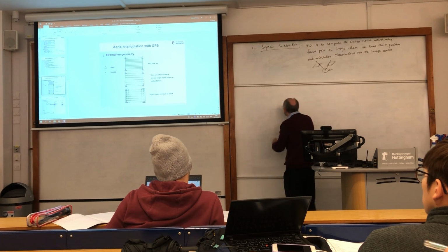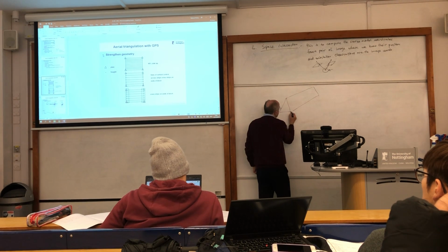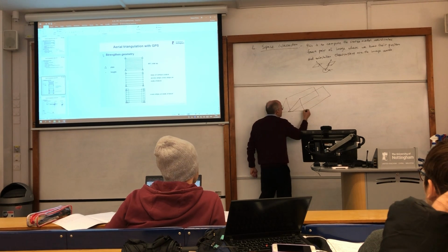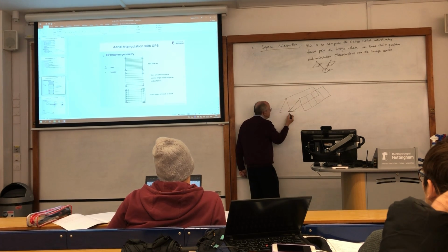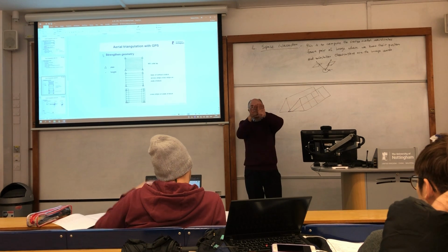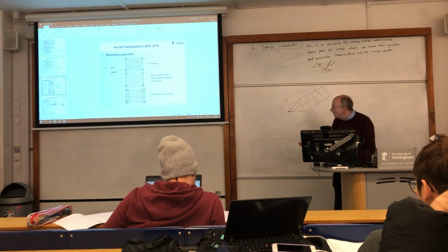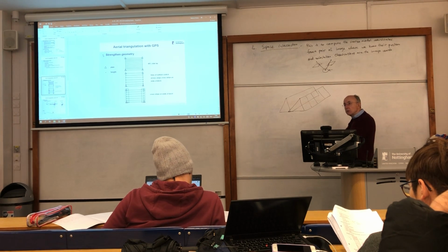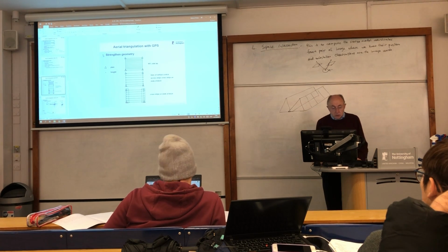Remember, the photogrammetric images are weak along the strip here, because when we overlap, they're strong down the strip, because you've got these triangles making up the frames, but here it's weak because you've got that small overlap between the strips, and of course they can flex. It's as simple as that. Strange that we're talking about these things in physical terms, but that shows in the mathematics. So it's the mathematical modelling where you can see these things occurring.